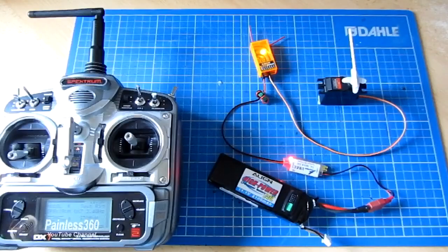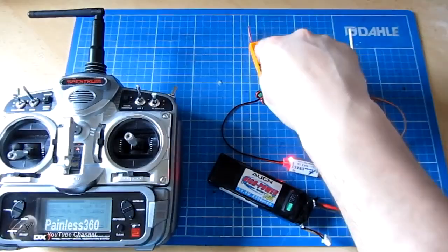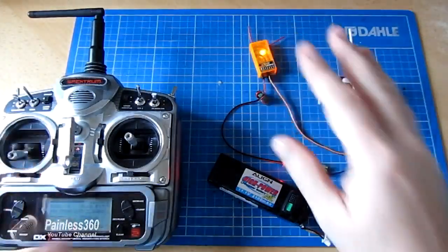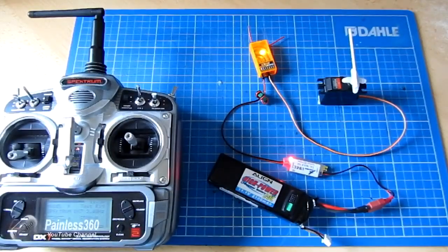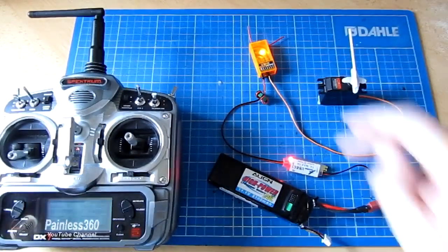Most modern radios, when you buy them these days, will come with one of these receivers in the kit. In the early days of remote control, the way that you got a receiver and a radio talking to each other, once you knew that they understood the same language, Spanish, English, German or whatever, is that you would put them on the same frequency. And there were particular frequencies, and the way it worked is that when you went to fly, you would be given a particular frequency that you could use for your flying time, and you had a little radio crystal that you'd plug into the radio that would change the frequency that you were transmitting on. There would also be a crystal that went into the receiver.